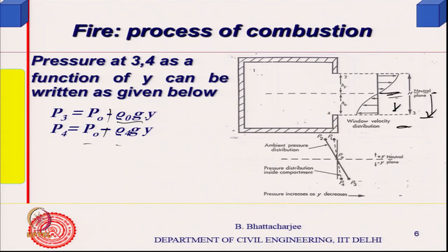So, this effectively becomes plus. Therefore, the difference would be this, because this is the larger value and this is the smaller value. Rho 4 is less than rho 3, y is negative from this datum, and P0 is the outside air pressure at the datum. So, the pressure here will be less than the pressure there, which I can take by taking y with a minus sign.